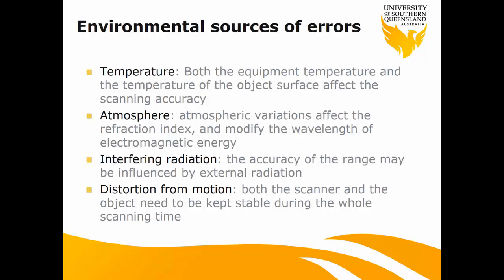Interference from other radiation sources. Since we use a laser beam, it could be affected by other radiation sources. Distortion from motion. If you use a scanning station for a long time, both the target or object you are scanning and also the instrument could have some movement. That certainly will affect your scanning result.